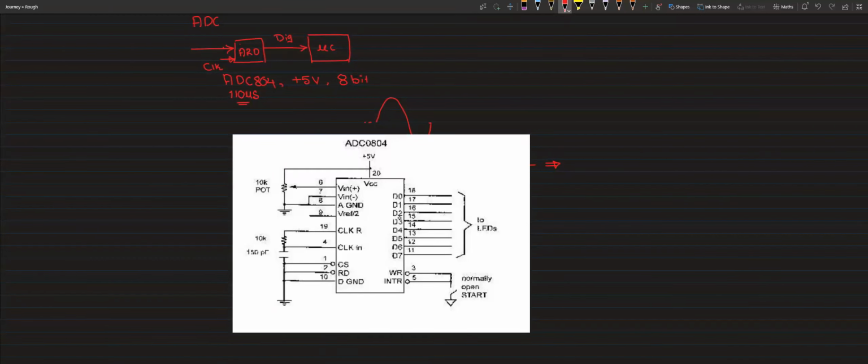So basically here the reference voltage, right, plus 5 volt, and you can see a pot. So you can adjust this V in. So this is the input basically. I mean, just to see those, instead of pot, here some sensors will be connected. So this voltage I am converting into digital value, and I am feeding the clock values also here.